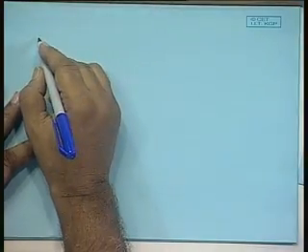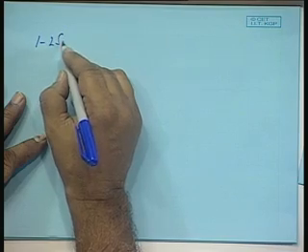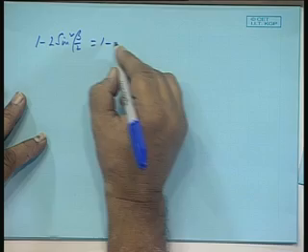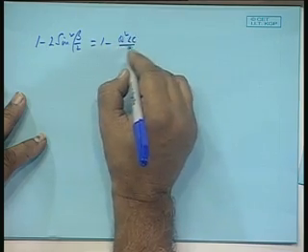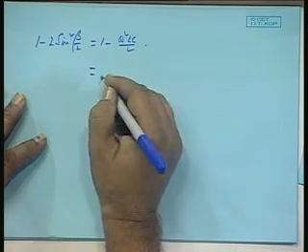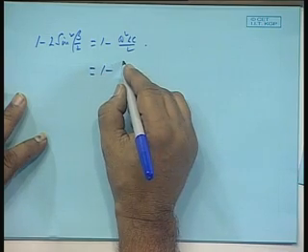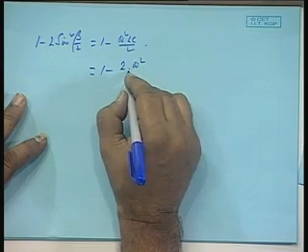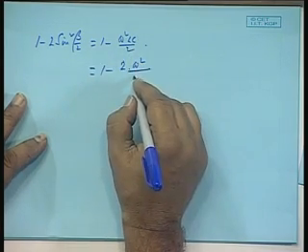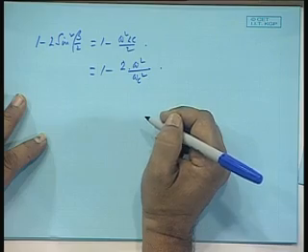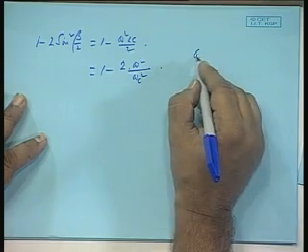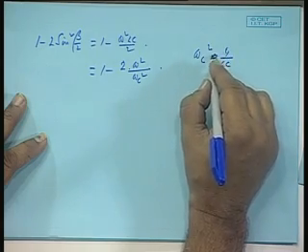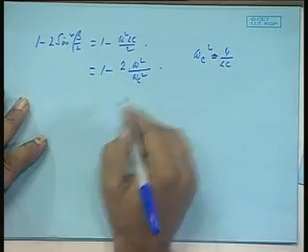So, cosine beta we can write as 1 minus twice sine squared beta by 2, and that is equal to 1 minus omega squared LC by 2, and we also saw this to be equal to 2 into omega squared by omega C squared. Therefore, because if you remember, omega C squared was 4 by LC. So, that gives me this.